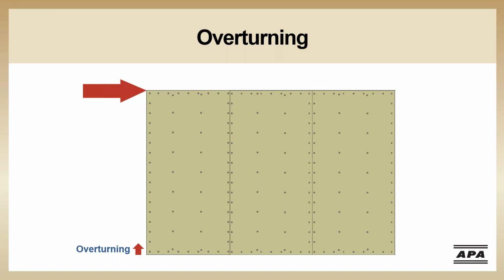Houses with limited bracing locations take the tall, skinny filing cabinet approach by usually using stronger bracing methods in order to minimize the linear footage of bracing, thus requiring hold downs. On the other hand, the prescriptive bracing section of the IRC, section R602.10, makes sure to require enough linear footage of braced wall panel to prevent overturning, thus eliminating the need for hold downs in most of the methods allowed by the code.